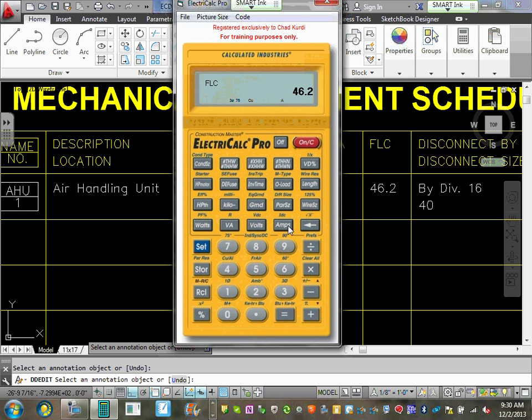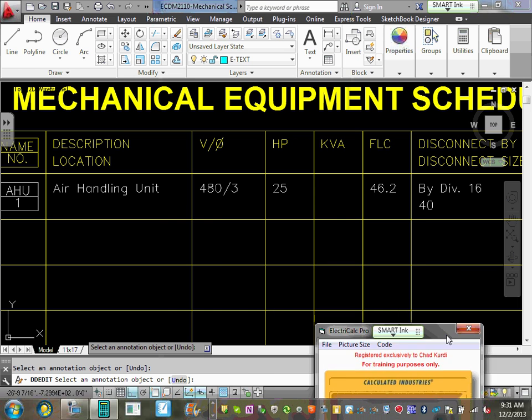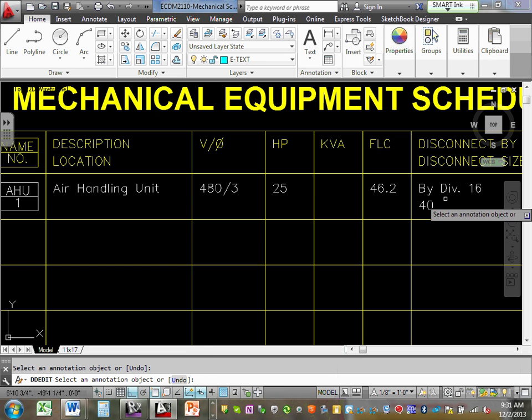Otherwise, you're going to go to Article 430, table 250. Let me see. If you click again on that, it should get you what the table is. Oops. All right, I screwed it up now. Click on it again. Doesn't give you much. Okay, so here's the information that you need from this. Okay, so 430, tables at the end. 250, yep, 250. Everybody knows how to use 250 to find the full load current, I hope by now, guys. We did a lot of these. Okay, I'm going to minimize this one, put it right here. Now, next, this is my full load. Next, let's go.